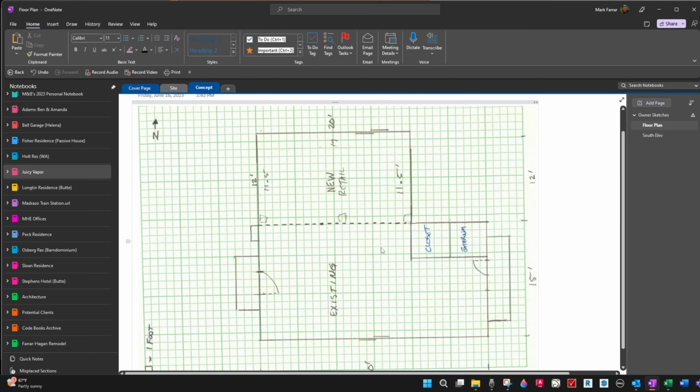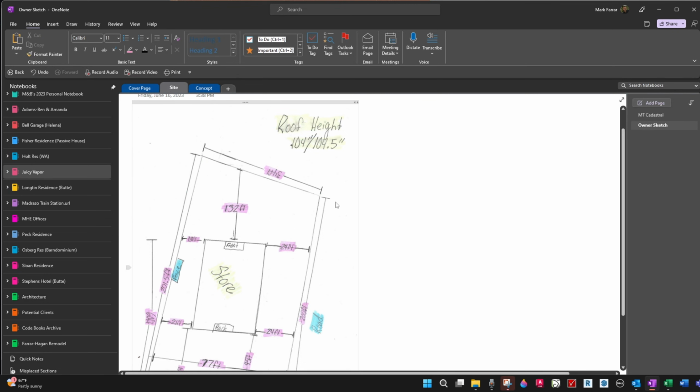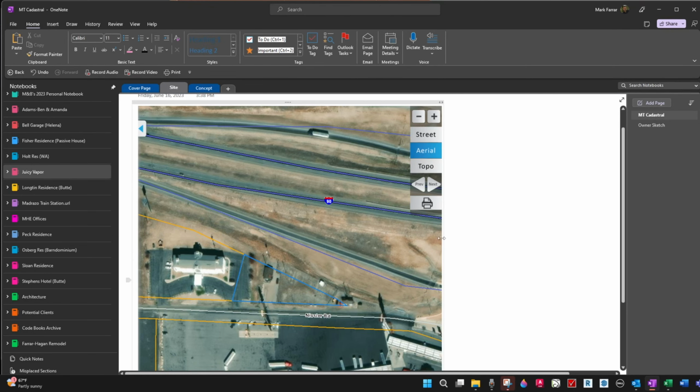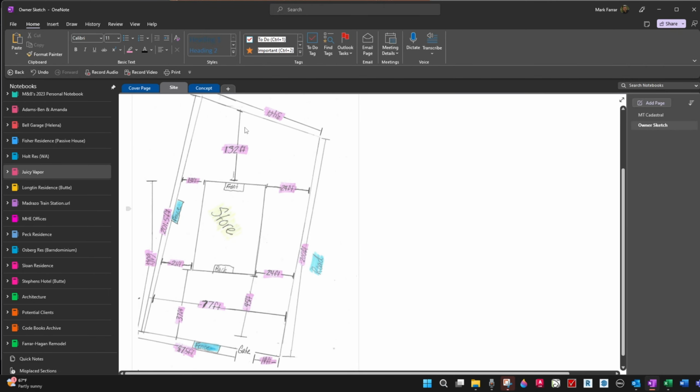What I'm concerned with mainly is if you look at the site, and not his sketch, but this guy, this building's right on the property line. Now, cadastral's pretty inaccurate. They're not what is called geosynchronized. So I wouldn't be surprised if this line is back here in reality. And their sketch shows a straight corner off that.